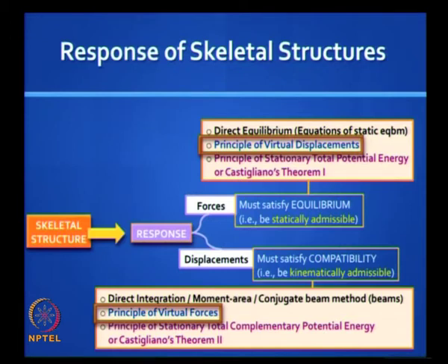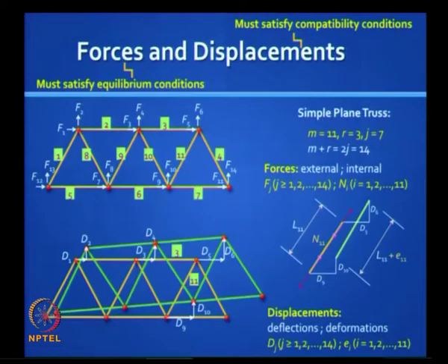So to find unknown forces in the force field which satisfy equilibrium, we can invoke the principle of virtual displacements, and to find unknown displacements in the displacement field, we can invoke the principle of virtual forces.